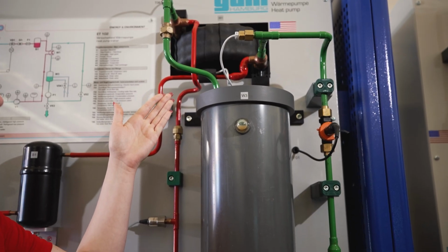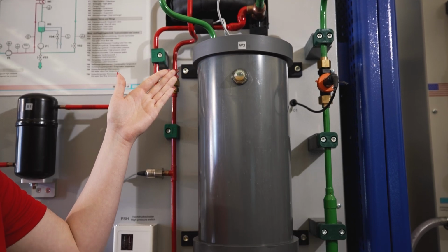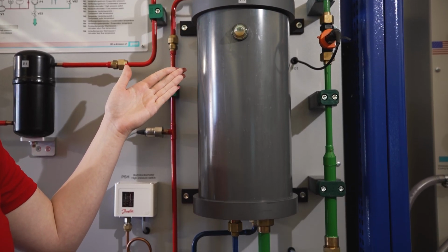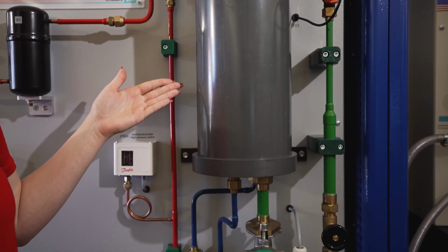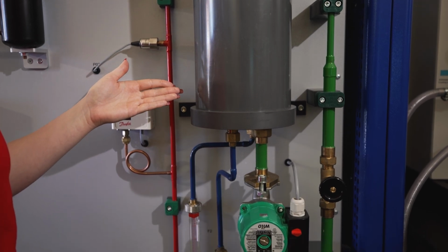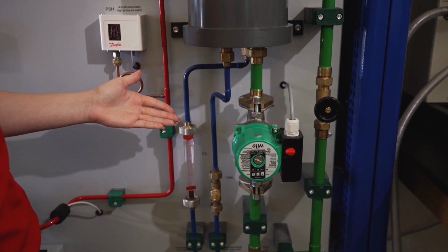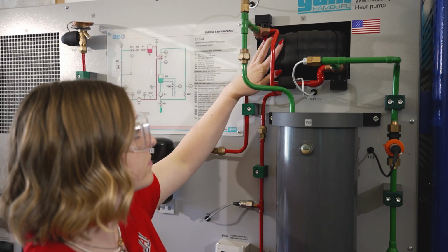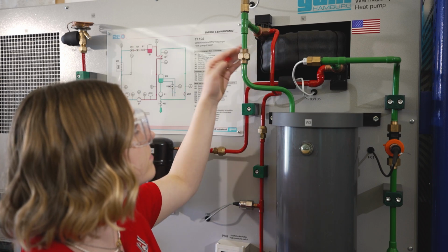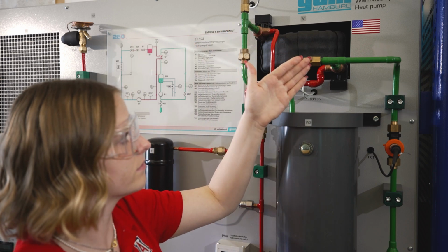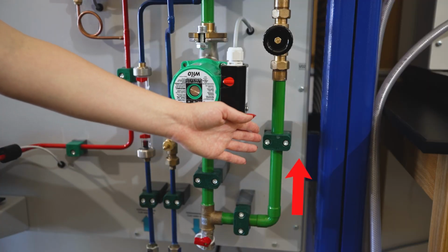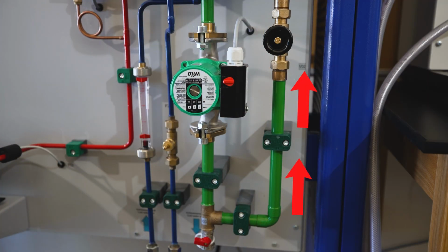The second system of the device ET102 is the external water circuit. The goal of this system is to take the thermal energy from the heat pump's condenser to heat up water. The external water circuit allows students to calculate the experimental coefficient of performance. The water circuit is composed of a heat exchanger pipe that runs internally and coaxially through the heat pump's condenser tubing. The water runs in opposite directions with respect to the refrigerant flow, that is, in a counterflow configuration.